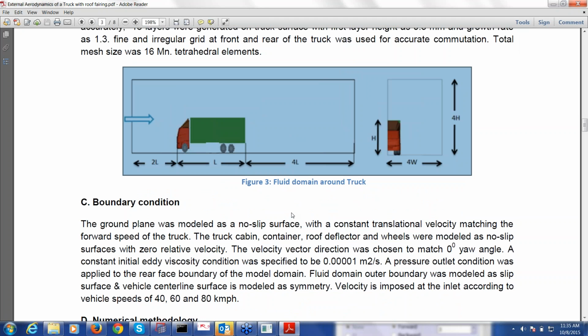So this is how you should basically build the wind tunnel. You can Google how you need to model the wind tunnel, and you will almost receive the same part. Basically, with the length of your car as L, the inlet should be 2L and the outlet should be 4L, plus the height and width. Make note of it, and make sure that you build your wind tunnel accordingly. These are the standard dimensions for doing aerodynamic CFD analysis in any software. So you need to build your wind tunnel something like this.